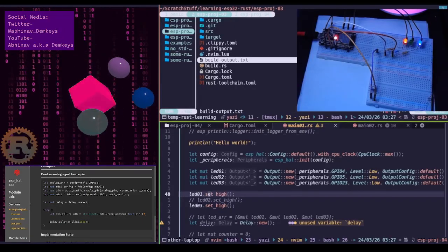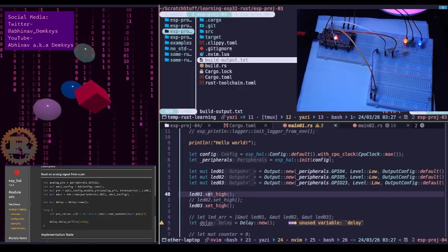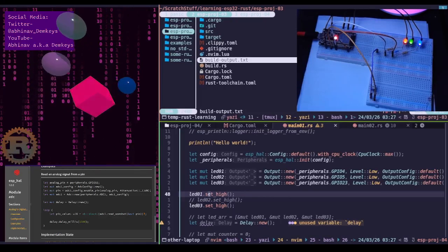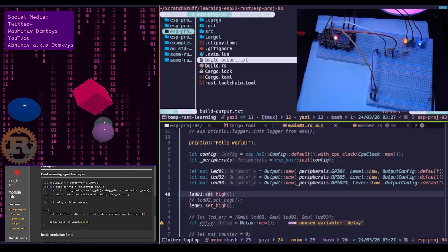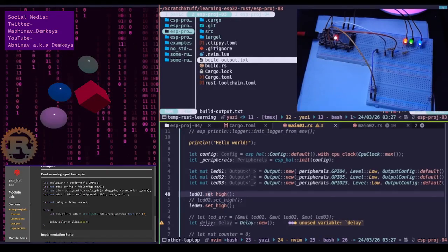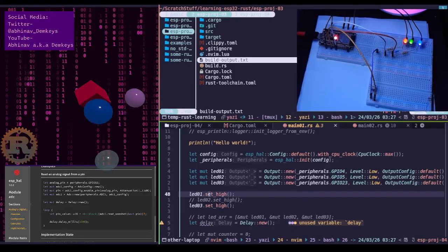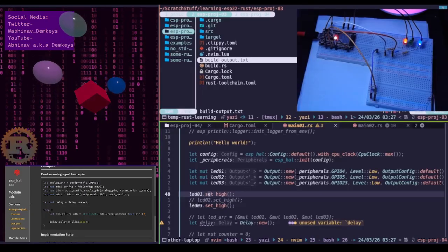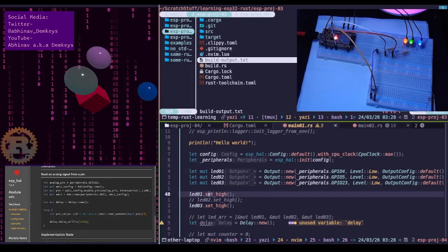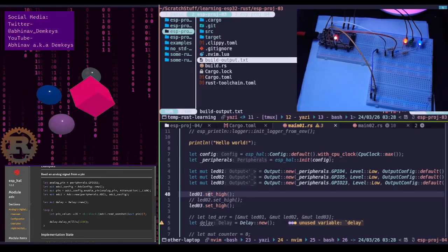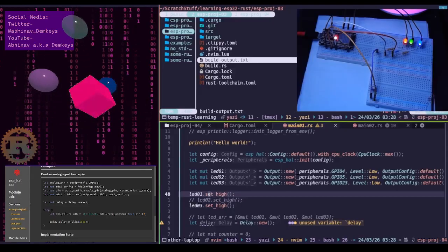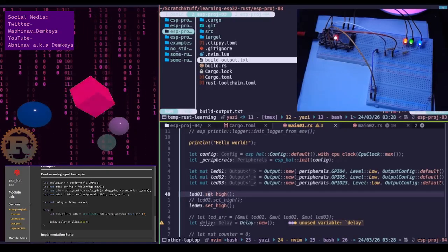And also, in terms of binding, assuming you've gotten rid of the oxidation well enough, and assuming heat is transferring well from the soldering iron to the wire, you won't have trouble getting the solder to bind to the copper.